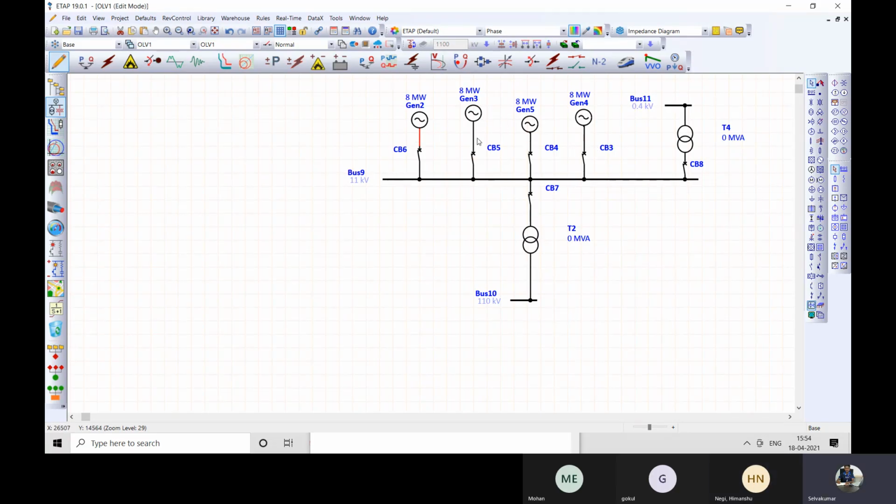Yes. That's applicable for all the faults anywhere in this place. Correct? And that's very critical. Like here, it is generator. This transformer has the grid contribution plus all the 4 generators. So a fault at this transformer HV terminal is more stringent than any other cases.